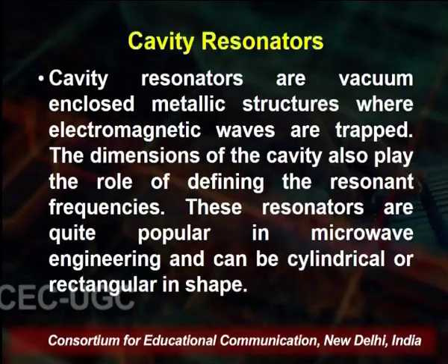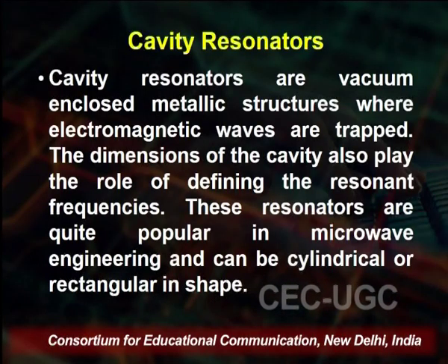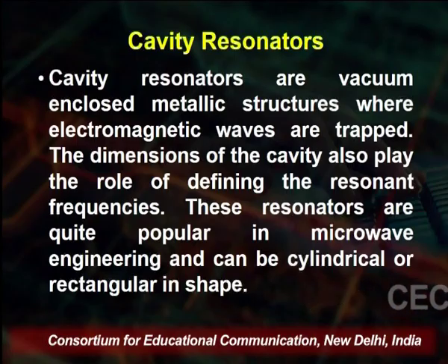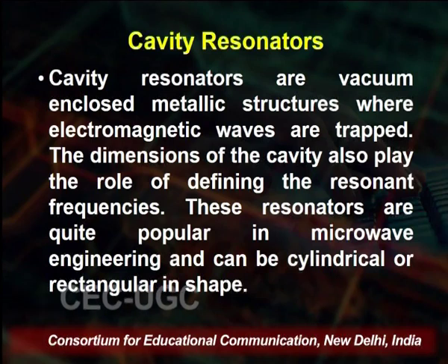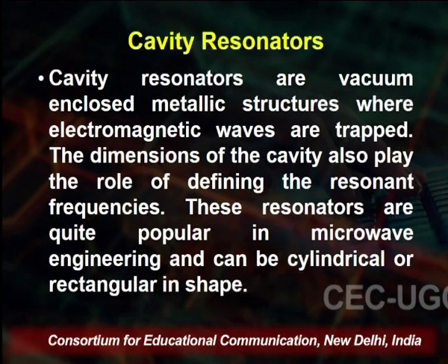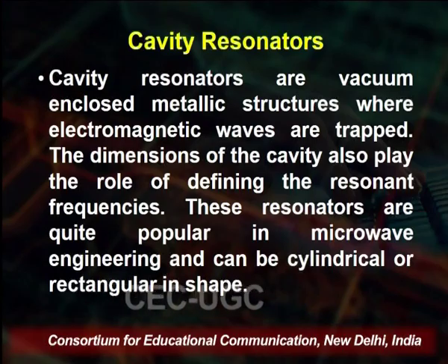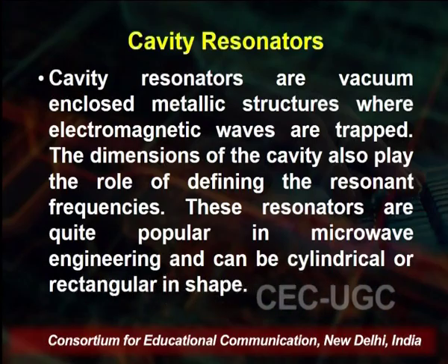So, first is the cavity resonator. Cavity resonators are vacuum enclosed metallic structures where the electromagnetic waves are trapped. The dimensions of the cavity also play an important role in defining the resonant frequency. These resonators are quite suitable for microwave engineering and can be cylindrical or rectangular in shape.